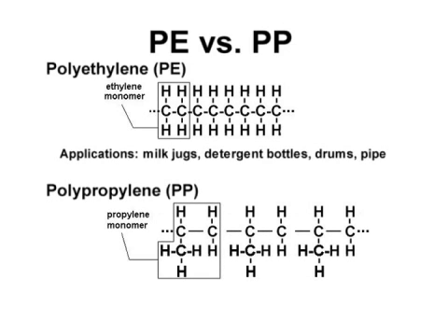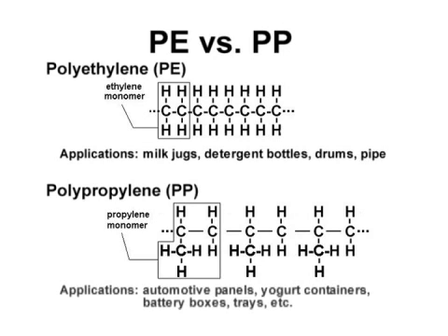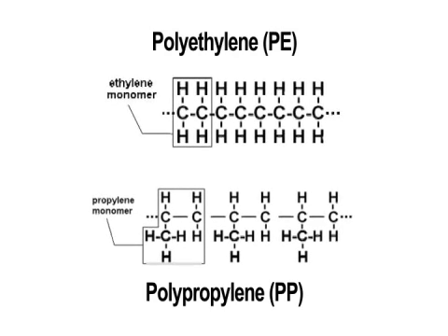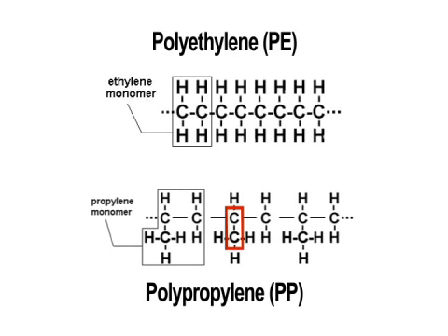Polypropylene is similar to PE in its molecular makeup with the addition of a carbon methyl group hanging above and below the central chain. Both materials in this finished form, pipe for us for sure, are typically a homopolymer with additives. Polypropylene is commonly used in applications requiring higher stiffness and higher stress crack resistance than polyethylene. One of the key drivers in stress crack resistance for polypropylene is the carbon-to-carbon bond in the molecular chain. In the simplest explanation, it's harder to strip carbon from carbon than hydrogen from carbon in a polyethylene chain.